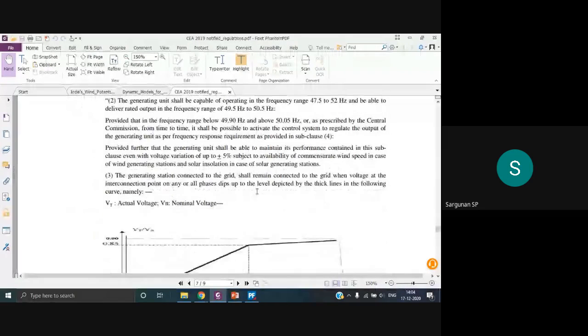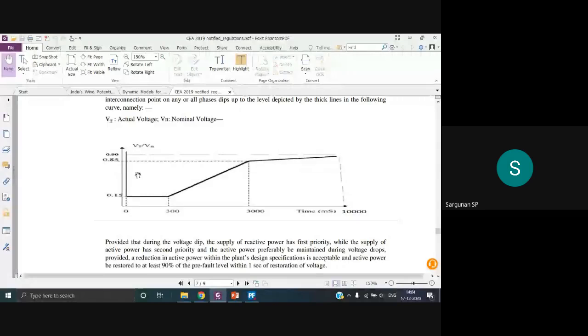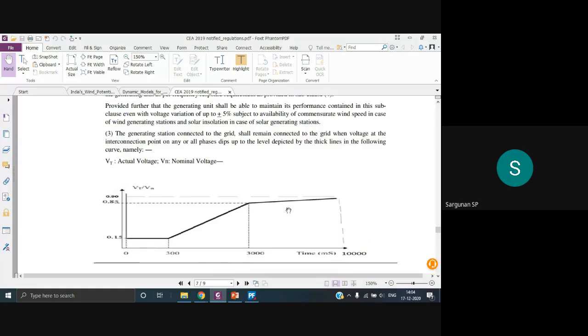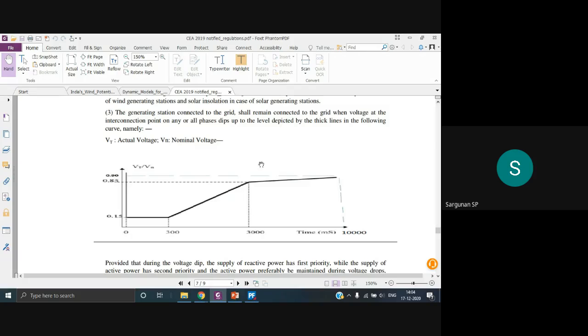Here you can see, for example, if I have a wind farm, normally this wind farm has a very low short circuit power. It will normally be around 110 to 150 percent of the rated amps of this wind turbine. But when compared to other generation, like your steam turbine generator or gas turbine generator, the short circuit power provided by those will be very high. But with these renewable sources, especially solar or wind, the short circuit power provided is very low. So that is one of the major disadvantages of going with these renewable energy resources.